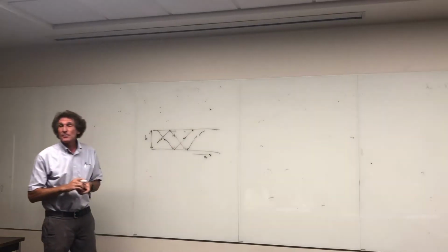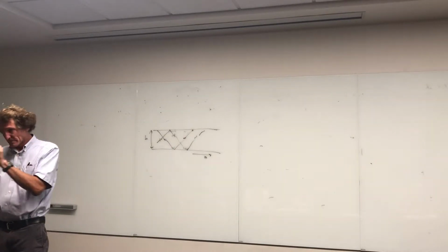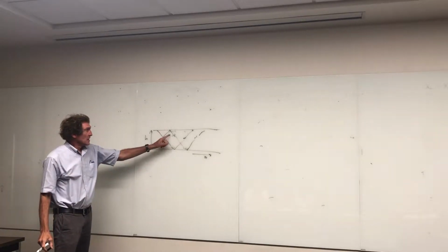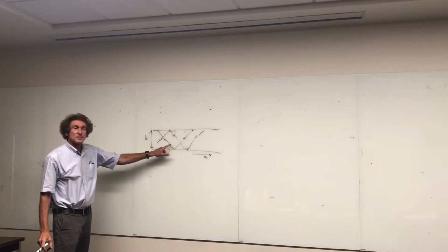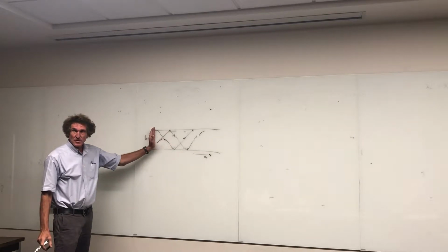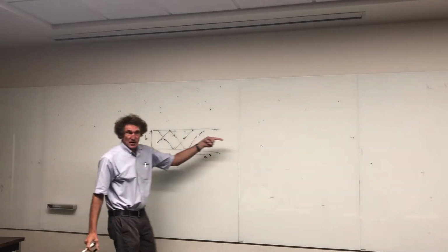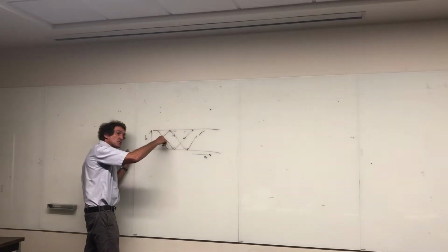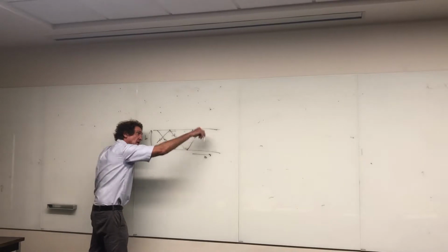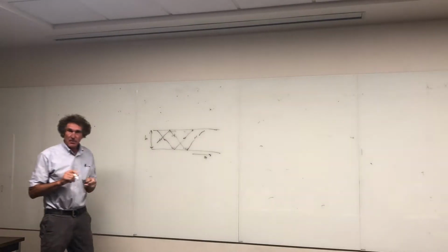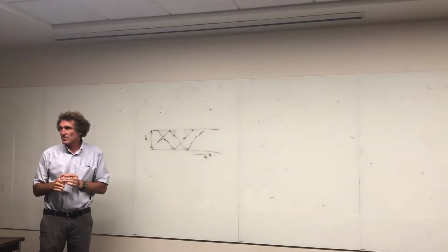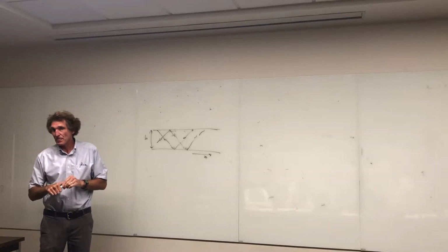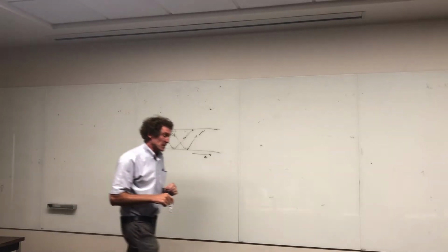That's how they say that if you take two plane waves where the same angle of incidence is the same angle of incidence here, and you phase them right, what do you notice? That you get propagation this way. Y'all follow me in that? Even though there's propagation in this direction for an instant, it bounces, so the net effect is propagation down that way. All right, class? Now that's what a waveguide does. It focuses all the electromagnetic energy to propagate in one direction. Got me on that? We'll be talking about a few other effects of this.